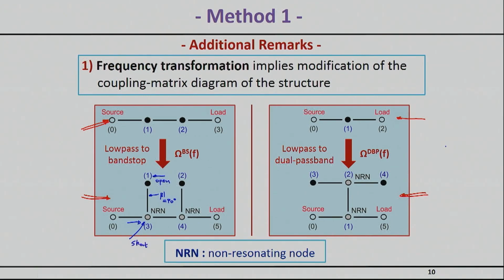Exactly the same thing will happen from the second resonator. So an initial open response at resonance through this inverter of 90 degrees will actually be translated now to a second short. So as you can imagine now, as the RF signal is propagating from the source to the load, it will face a reflection here. So here's your first band stop hurdle, let's say, and whatever little leakage you might have will actually face another response from here.